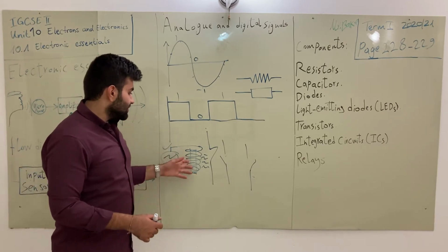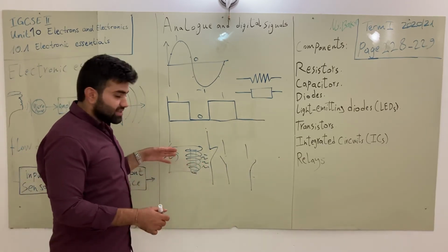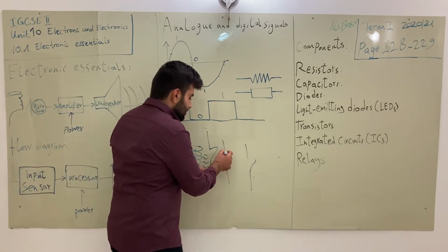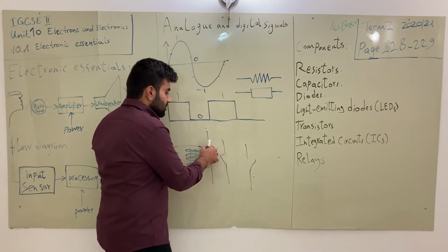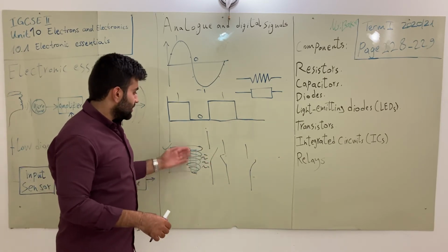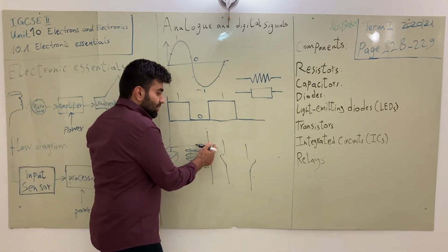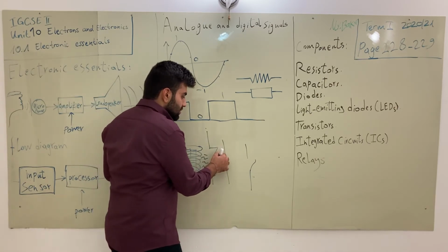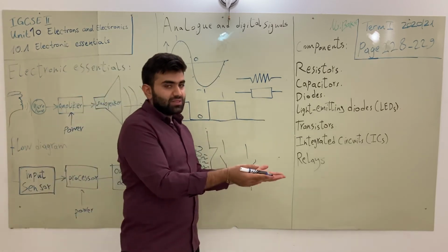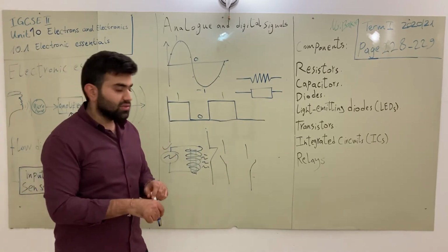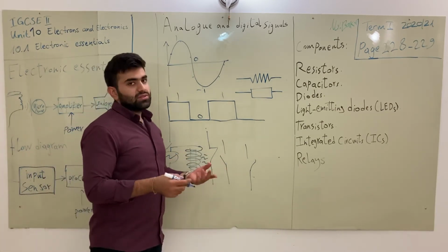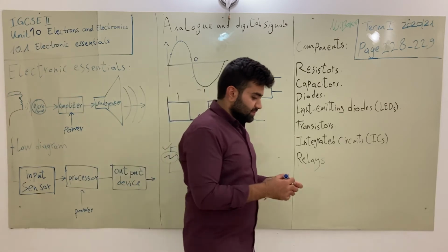Okay? So similar to that, when this has a magnetic field, when I apply electricity. This one is normally closed, and this one is normally open. In the normal way, without electricity, it's like this. When I apply electricity, the open will be closed and the closed will be open. When it's closed, that means it gives us the current or the electricity, and when it's open, it doesn't. So you see there are two switches here. There's a relay with 1, a relay with 2, a relay with 3, 4, etc.